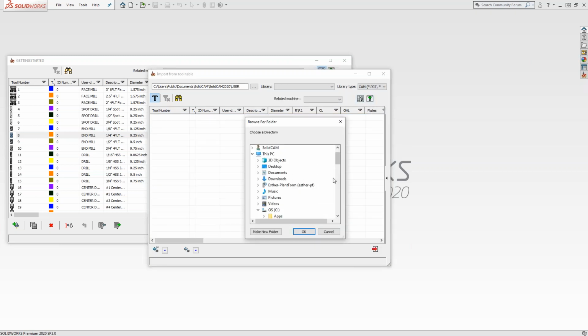In that specific case, we can't do just the holder, because the local library is not set up to create a custom shape holder on the fly. It's set up to modify the library, but not to completely build it. So what you could do is take a screenshot of the dimensions of that holder that you made changes to, and then put those in there. But there's no way to export just the holder out of a local library.